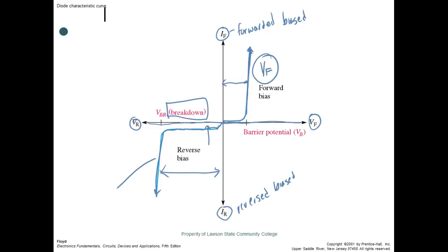on purpose. So that's one of the things we do when we choose a diode. One of the things in the specification is the breakover voltage. And you want to make sure, and that's a voltage. So, you know, when we deal with RMS, we don't understand peak, but this is a voltage. It's not an average voltage. So, if you've got 120 volts RMS, and you use a diode that's got a breakover of 120 volts, you're going to bop that thing because it's got almost 170 volts peak, right? You understand that? So that's one reason you need to be able to figure peak voltage.